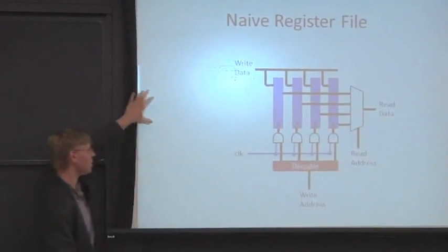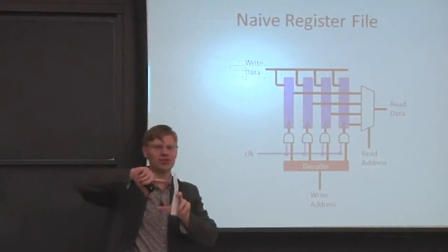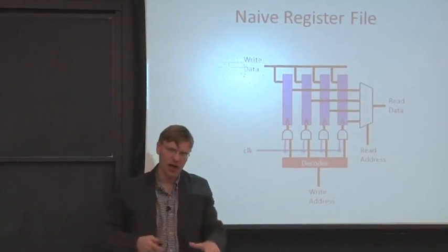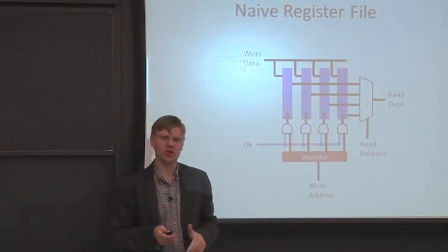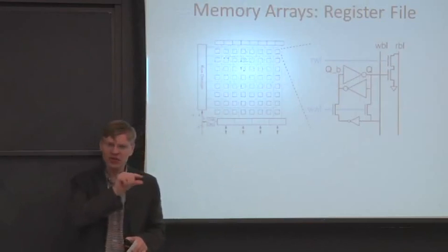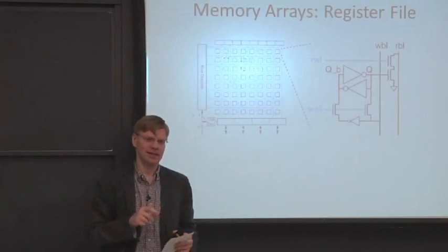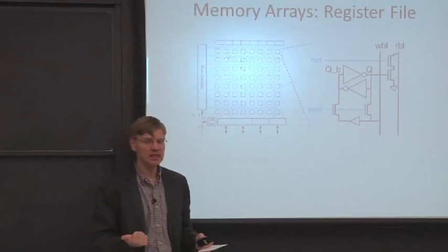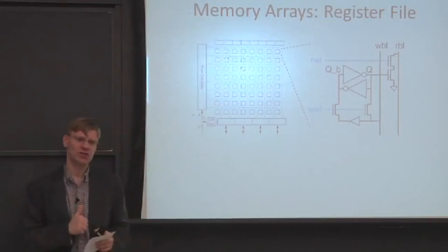And if you stack these all up, 1,000 long, your aspect ratio, your x versus y, or the size when you go to lay it down on a piece of silicon is very long and very narrow. So you'll end up, let's say, with 1,000 bits, 1 bit tall. And that does not lay out very well, and it's not necessarily good for speed or from an area perspective. So why is it not good for speed?